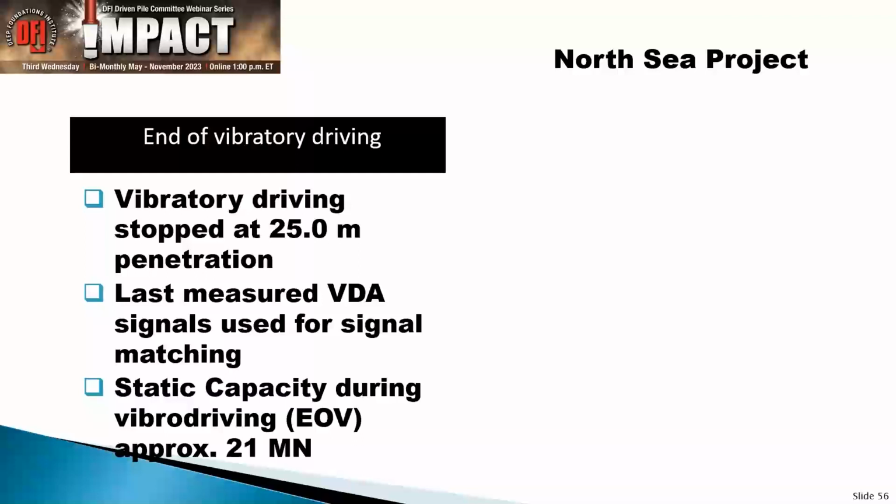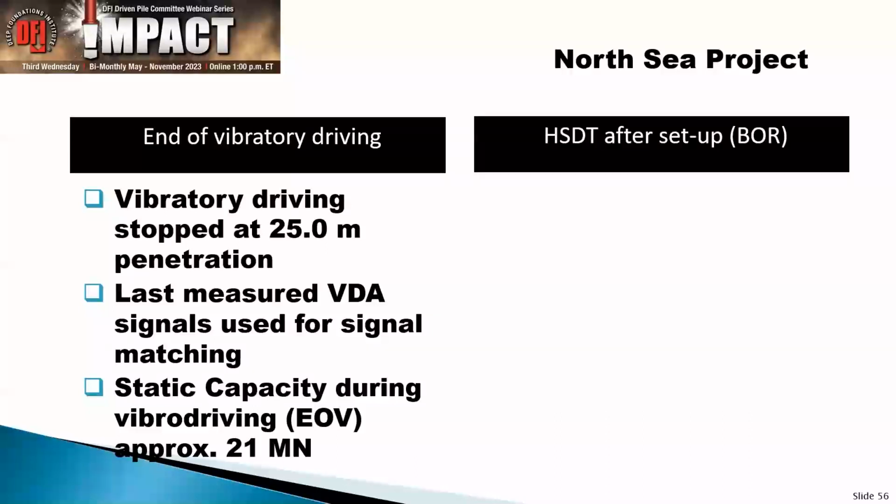So we were somewhat embarrassed, obviously, that something was not going right. But okay, fine. At least we know what's happening. And besides, when we did the new soil model, we got a much better indication that our soil model was initially not all that good. But we also saw this as an opportunity, because now at the end of vibratory driving, what we normally call the EOD type signal match, call it here end of vibratory driving, EOV.